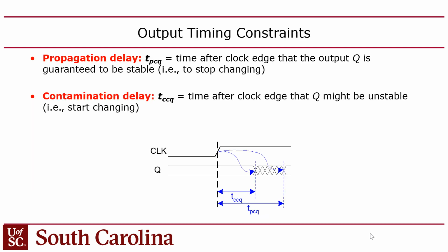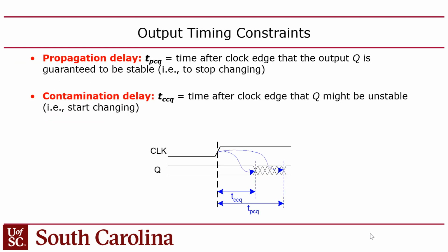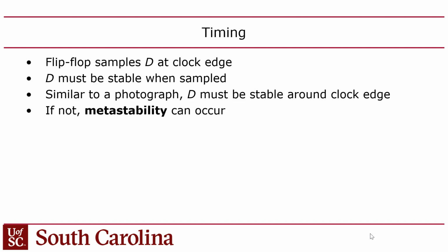And okay, the reason for that is generally you have the gates inside your circuit, you're going to have data paths in your CPU, meaning that the logic is set up to where the inputs of the logic come from a register, and the outputs from the logic go into a register. You guys with me? So you start with a memory element and you end with a memory element. Okay, and so these are data paths in your CPU.